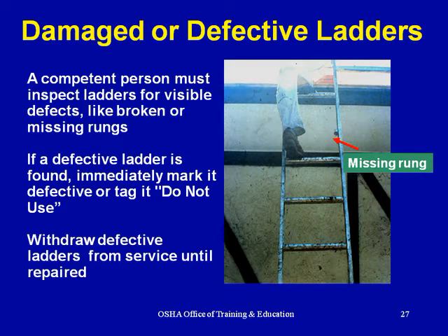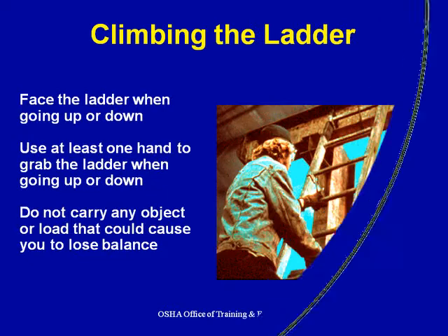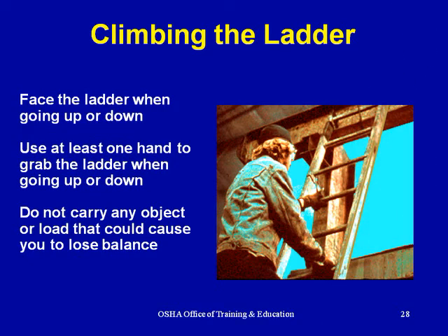Damaged or defective ladders. A competent person must inspect ladders for visible defects like broken or missing rungs. If a defective ladder is found, immediately mark it defective or tag it. Do not use. Withdraw defective ladder from service until repaired. Example of missing rung.